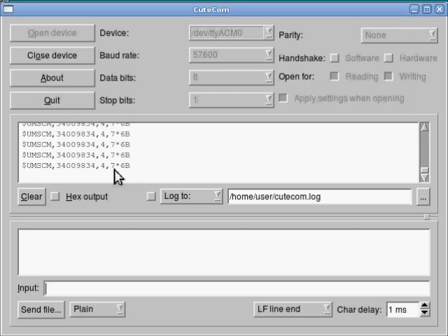This is not actually connected to a load, so it's been reading 7 kilowatt hours for quite a while now. The asterisk shows that that's the end of the data elements, and then the last 2 characters are a hexadecimal checksum. This is an ASCII value. You can recompute the checksum for any sentence by doing an exclusive OR on the ASCII values of all the data fields, including the commas. Very simple to recompute. And that's basically how this data works.